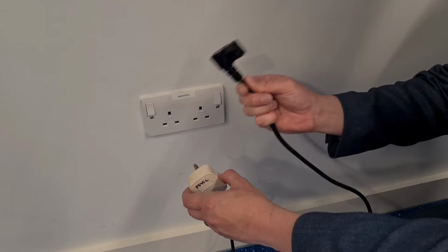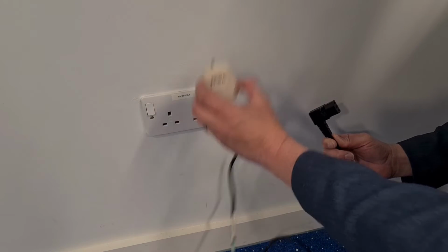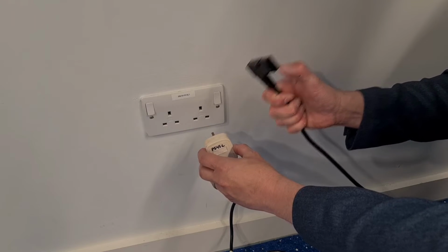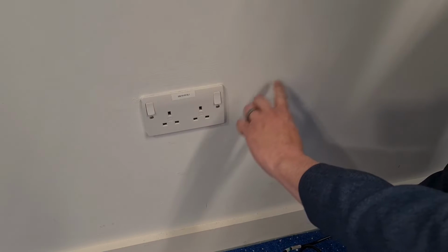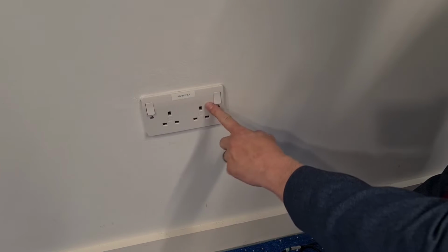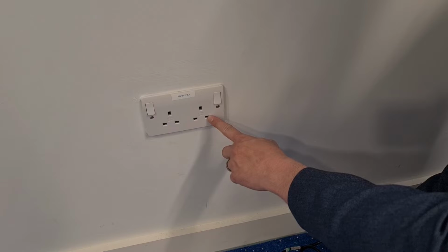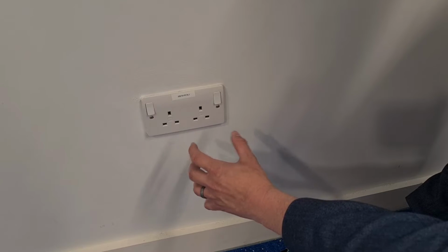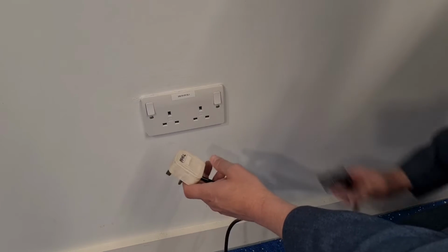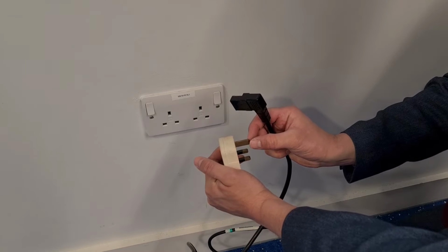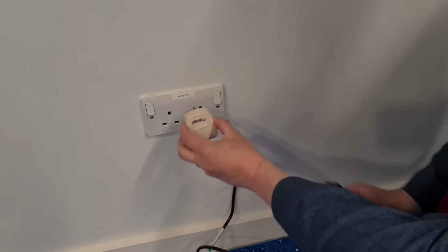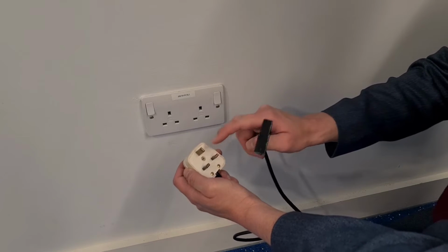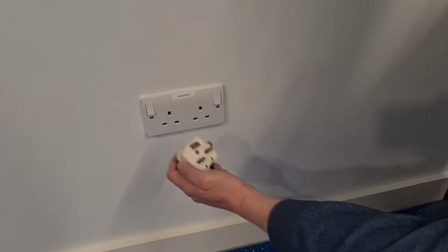Here is an issue. The other end of the wire might become live, even if it is correctly wired, and we plug it in here, with an amount of electricity that, if touched, would be fatal. So one thing you can do is press the circuit breaker and disconnect all of the sockets in the room, just to be sure. Also, instruct pupils not to plug it in. And thirdly, you could tape up the other end of this, and I have also seen you can bend this earth pin so that it isn't possible to actually get it into a socket. Either way, be careful, but it's worth doing because you need to know what is inside this plug.